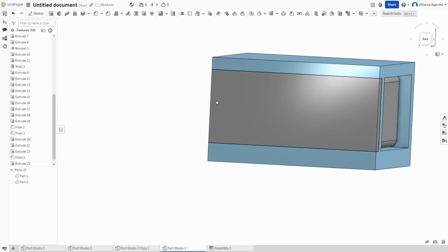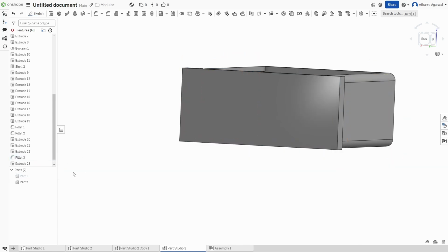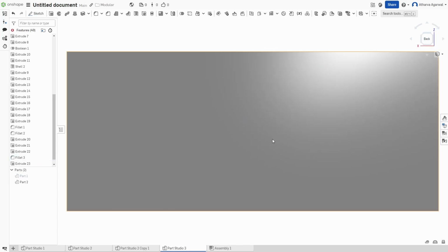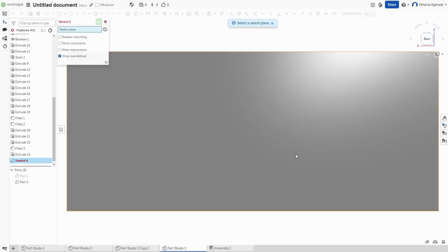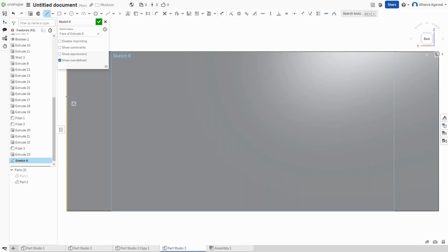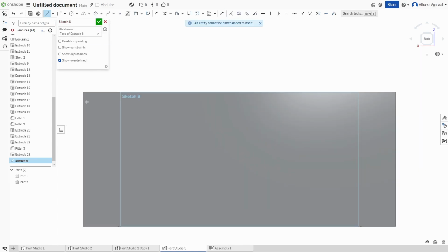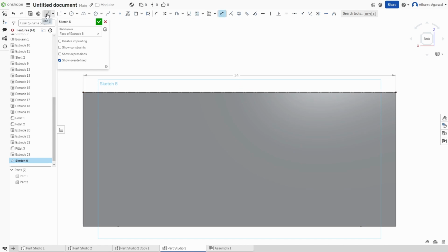But now you might be wondering, how will I open it? So to get over that, I'm just gonna be coming over here. I will be creating a new sketch. Create a few quick construction lines. Create a construction line from there to there to get the size, construction, and then dimension. Do the exact same for the vertical axis.